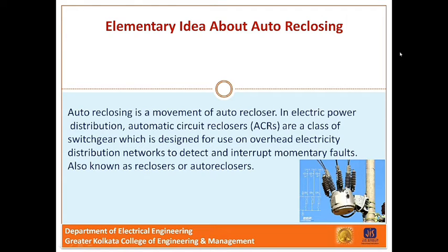For overhead distribution networks, the majority of faults are transient, such as lightning strikes, surges or foreign objects coming into contact with the exposed distribution lines. By this logic, 80% of the outages can be resolved by a simple close operation. Reclosers are designed to handle a short close-opening duty, where electrical engineers can optionally configure the number of attempted close operations prior to transitioning to a lockout stage.